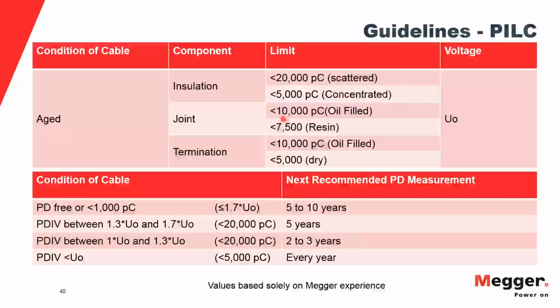And you can go through this as you go through. A cable that's not very critical but is in good shape, maybe we only want to do diagnostics every 3 years. We want to make sure that it's not aging too quickly. But this is pretty common sense, pretty straightforward, but you guys can take a look.